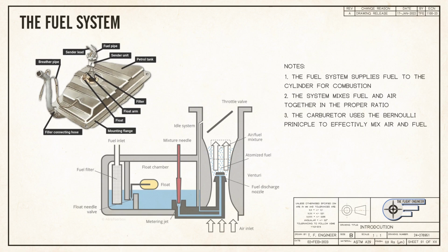Inside a carburetor, the throttle valve allows for the operator to meter the flow of air into the engine. This intake air passes through a restriction known as a venturi. This causes airflow to increase in velocity and, by Bernoulli's principle, decrease in pressure. The low pressure creates a suction that pulls fuel through jets so that it can vaporize and mix with the intake stream. This system is self-regulating. As greater amounts of air pass through the same restriction, velocity is driven higher and pressure is driven lower, so more fuel can be sucked through the jets.